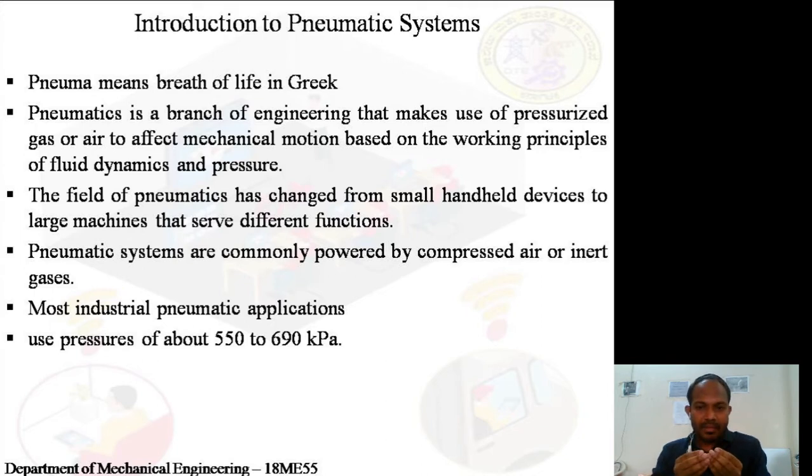It is only because of the beauty of the fluid, with the load being applied onto this stone irrespective of the geometrical irregularities. That is the beauty of fluid systems, whether I'm talking about a hydraulic system or a pneumatic system. The beauty of fluid power systems is that the force is distributed uniformly. That is what our Pascal's law states. My dear friends, Pascal's law obeys for both hydraulics as well as pneumatic systems.